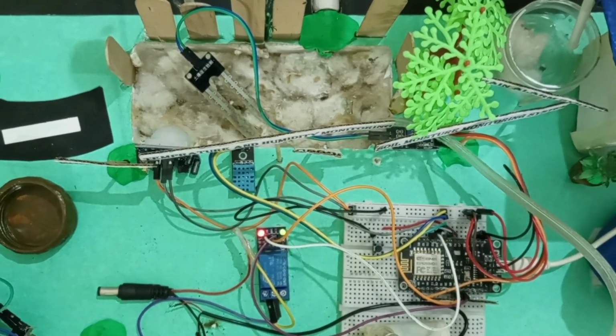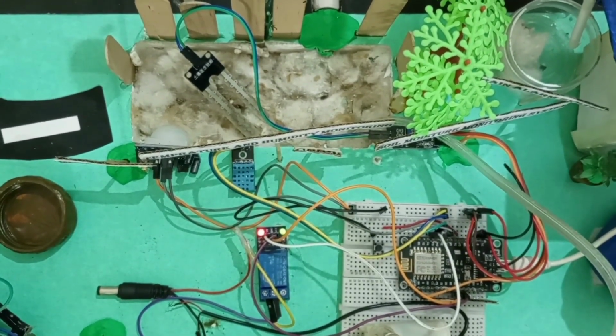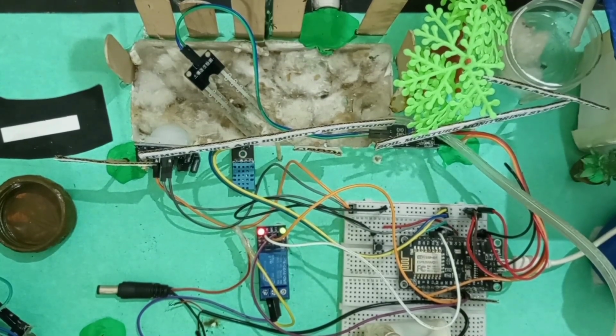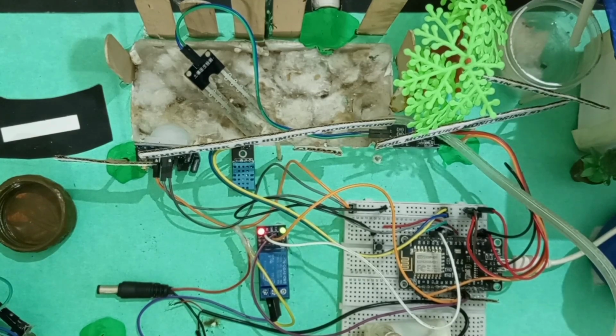It has temperature and humidity monitoring, motion alarm, soil moisture monitoring, water pump, a relay, and an ESP8266 board. So the temperature and humidity sensor sends temperature and humidity to the farmer's mobile dashboard. The soil moisture sensor does the same thing for the soil's moisture. The water pump is used for irrigation. The PIR motion sensor is used at night time to identify cattle or any animals entering the farm.